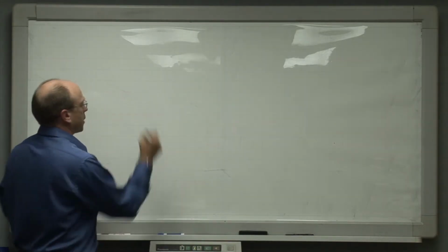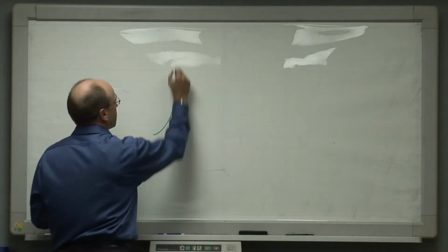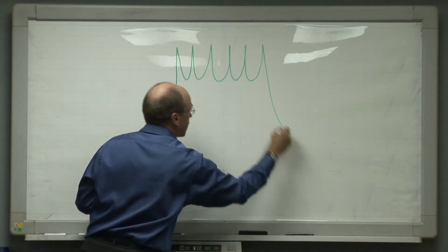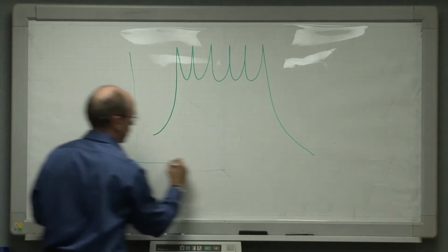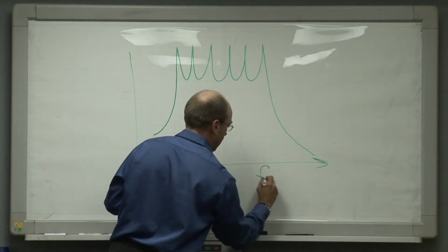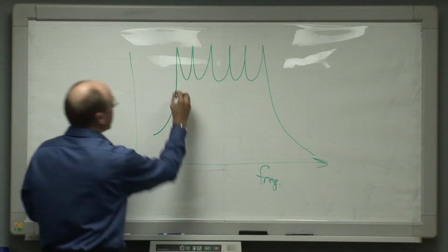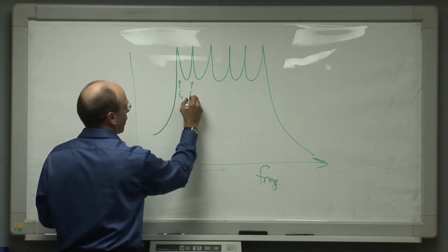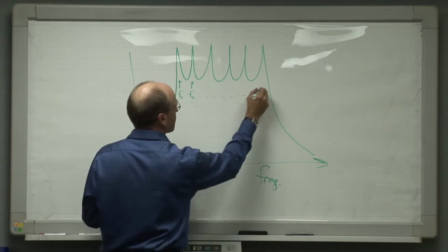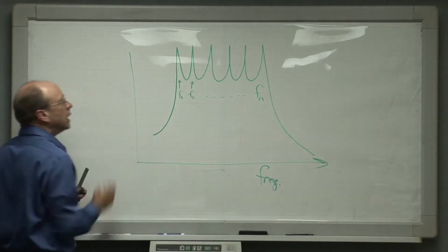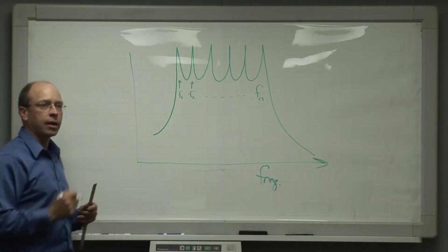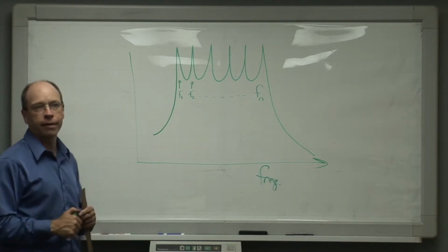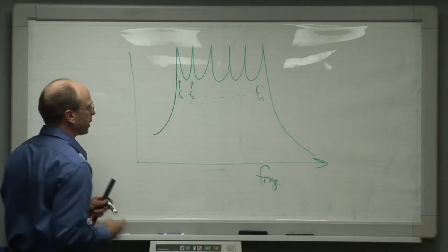Okay, we already discussed the fact that the radar emission spectrum, which may look like this with a bunch of separate frequencies, and then comes down like this, means that the radar itself may well be hopping from frequency 1 to frequency 2 and so forth across up to frequency f sub n on a moment-to-moment basis, every few pulses, every 5 pulses, every 10 pulses, every 20 pulses. It depends on how the radar is built. It may be switching back and forth in frequency.